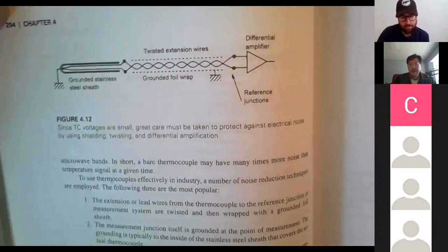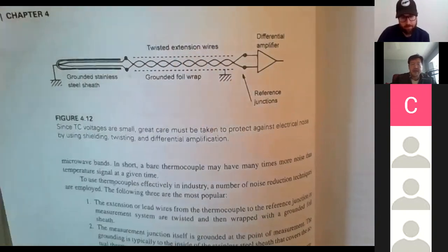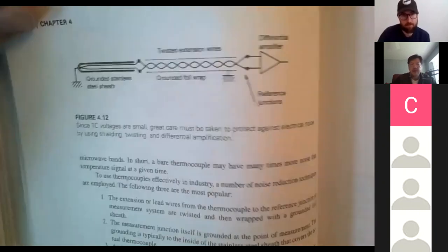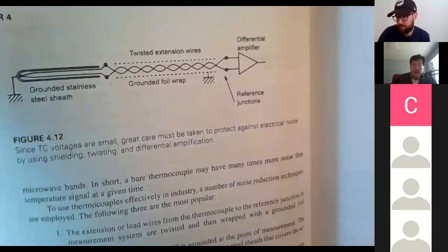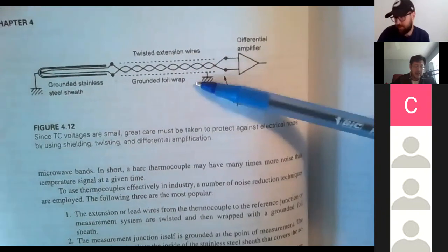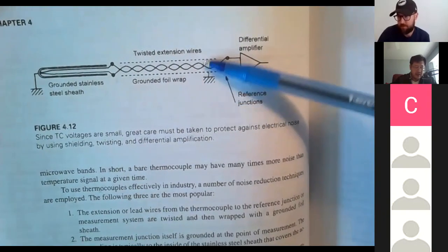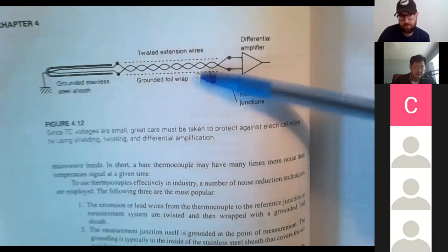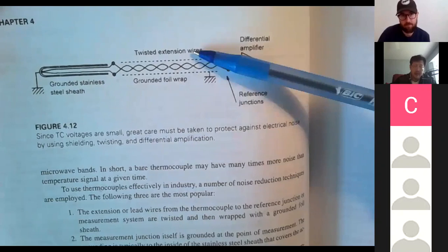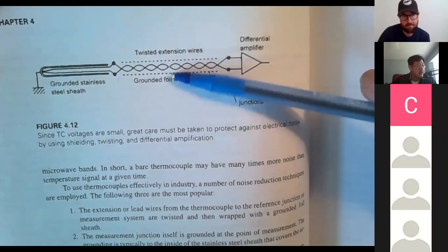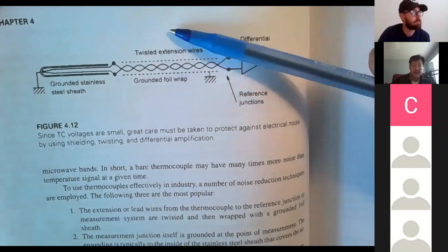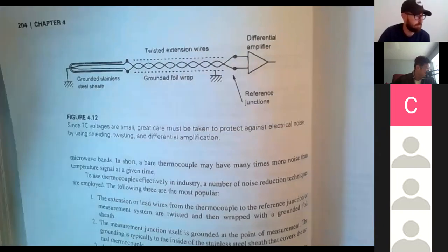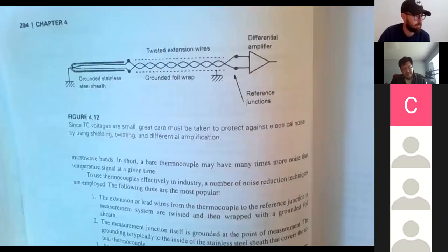So it's very important for the thermocouple sensors to reduce noise because the voltage is very weak. Otherwise, you will pick up radio signals, televisions, whatever power signals, 60 hertz. That's a huge noise, 60 hertz. So there is noise everywhere. You have to reduce that.